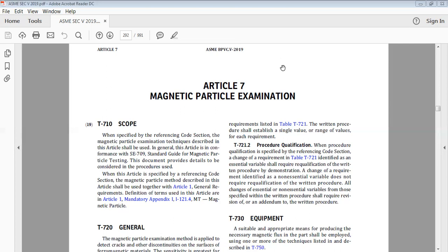In case of visible magnetic particle testing, meaning color contrast, regular magnetic particle testing, the concentration should be 1.2 to 2.4 ml per 100 ml. But for fluorescent magnetic particle testing, it should be 0.1 to 0.4 ml per 100 ml of bath. For fluorescent, your indication color will be yellow-green, and for visible, your color may be red or black.